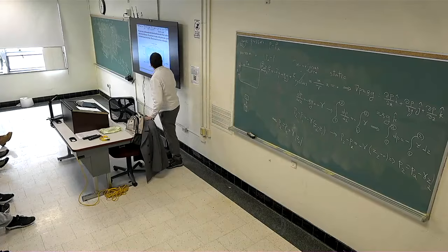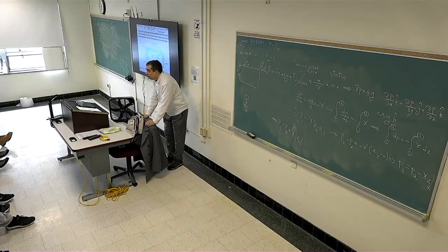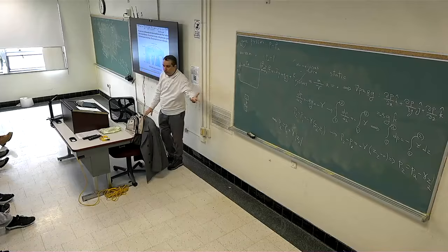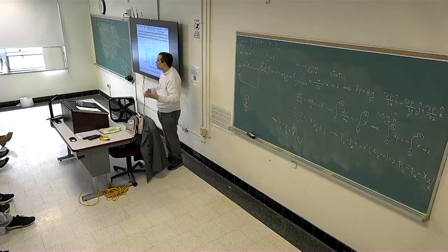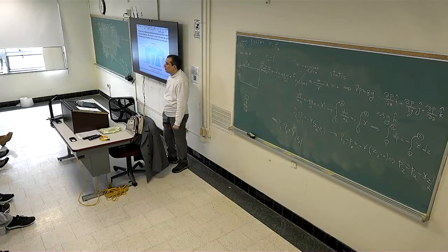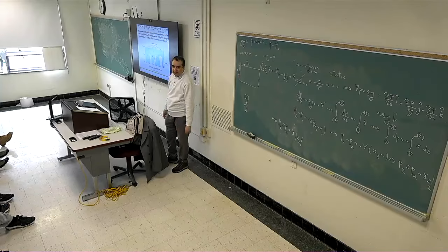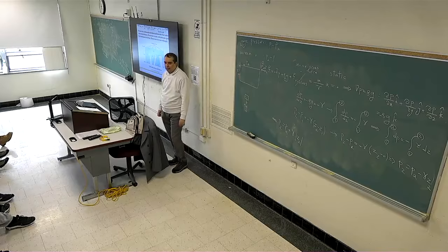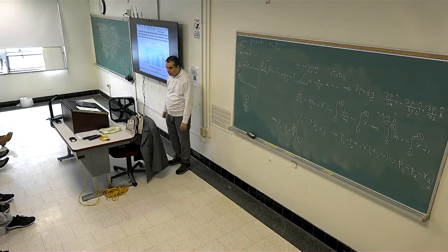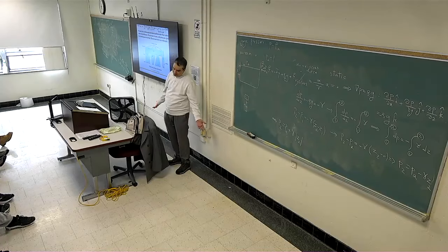Compare the pressure at C and D with the equation, not intuitively. The pressure at D is going to be greater than the pressure at C because mercury has a higher specific weight, so for the same amount of Z, it's being multiplied more.